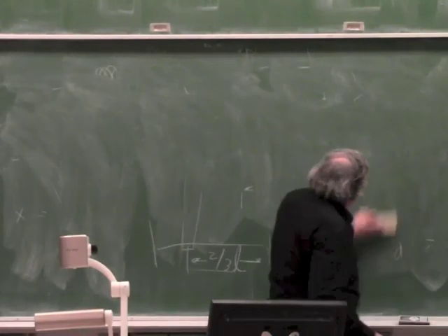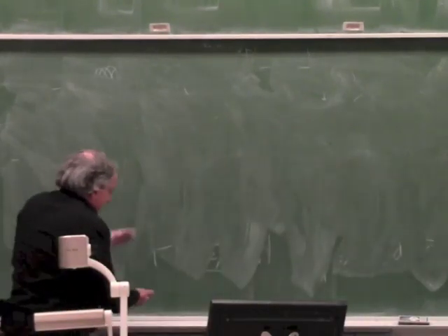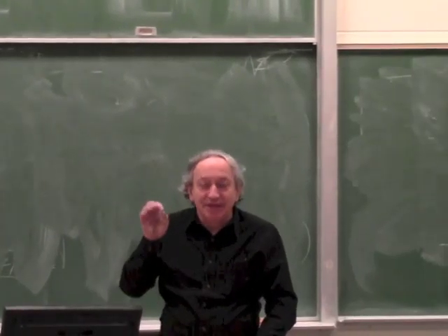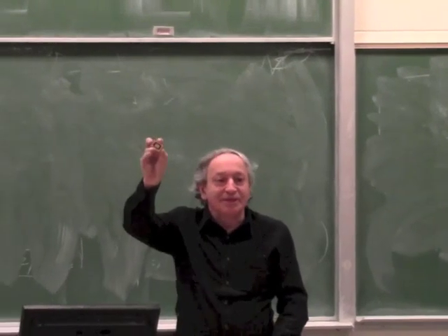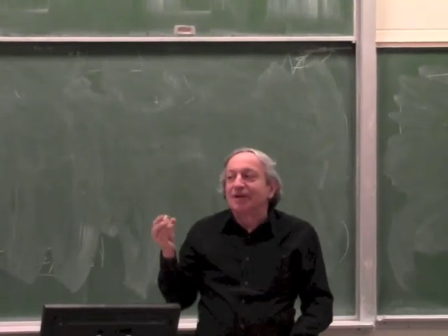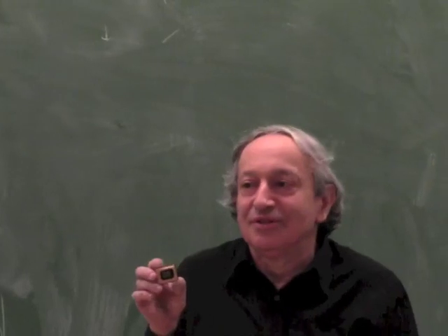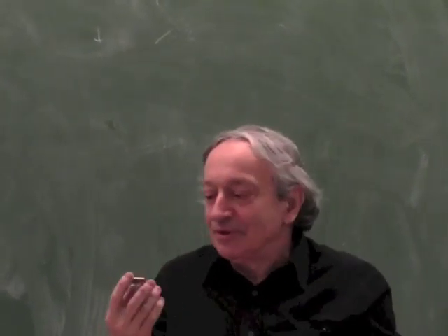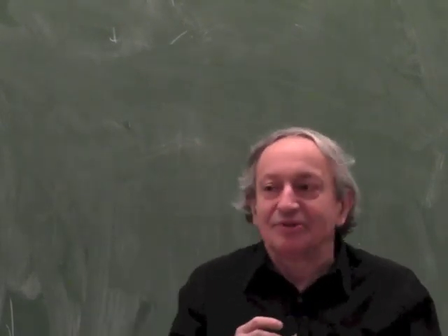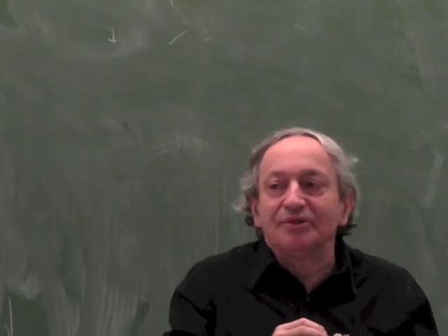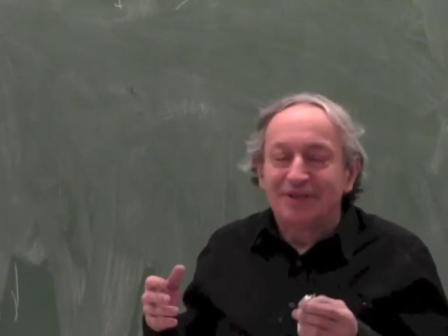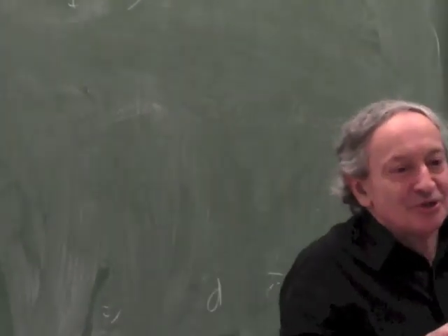The most popular electrostatic actuator in the world in terms of units made is this DMD or DLP. This is a chip which has 1 million electrostatic cantilevers, used in video projectors. When you look at it, it just looks like a mirror, but it's actually 1 million mirrors. And this chip has all the electronics to drive them: under these million mirrors there is memory, shift registers, interfaces, everything needed. So it's quite an amazing chip.